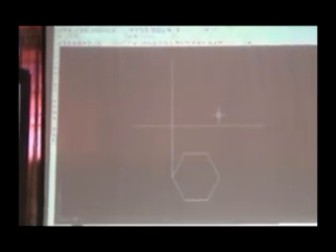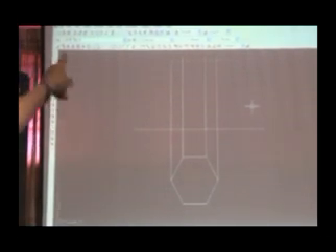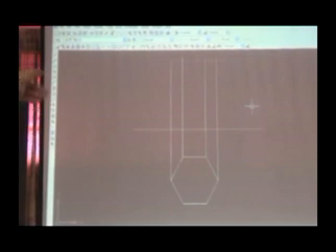Then suppose I want to draw a horizontal line. So again I am using line from here, extending. Then I want a line from here, that is again another projector line. I will have an edge from here. Right, so it is not correct. I want to trim some of the portions. It is not exactly the front view of that hexagonal prism. So which portions do I want to trim? These portions I want to trim.